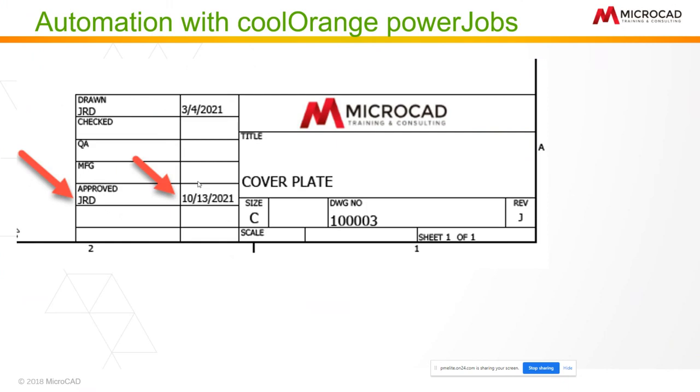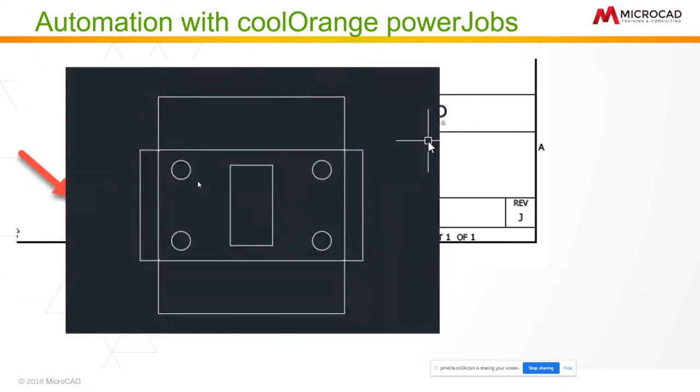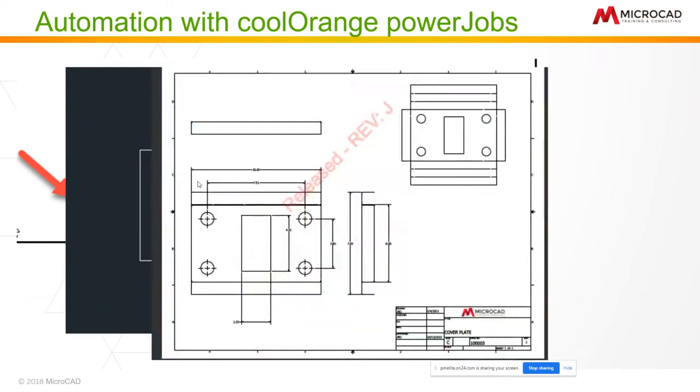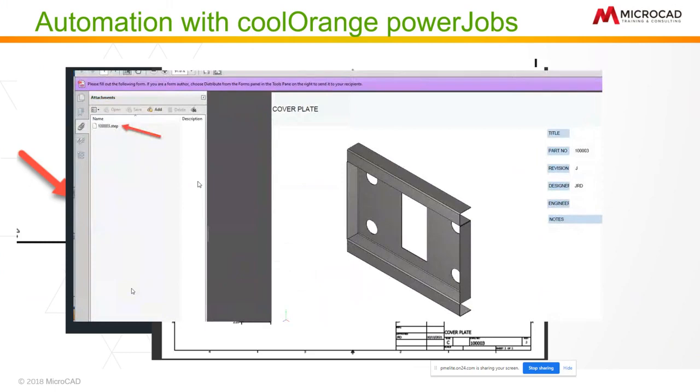It can create those sheet metal DXF files like this. So if it's a sheet metal part, it'll create a DXF file automatically. If it's an IPT file or an IAM, it can do watermarks on the PDF files. IPTs or IAMs can create a 3D PDF with an attached STEP file. So it just takes the capabilities of Vault and expands it, I don't know, 10 times, 20 times. It's exponential because if you can think it, we can do it. It's just a matter of what you want Vault to do when you release the document. What needs to happen? In this particular case, we want some of these processes to be happening in the background.